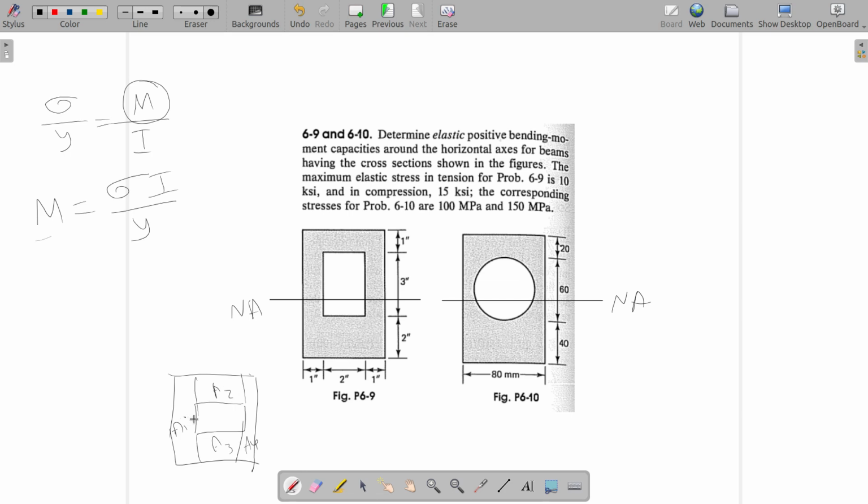and I can calculate the moment of inertia of these areas about their corresponding centroids. After that, using the formula for finding the collective centroid of the whole figure, I can find out the location of the neutral axis. Once I have the location of the neutral axis, I can add up all the moment of inertia values about the neutral axis and get the total moment of inertia about the neutral axis.